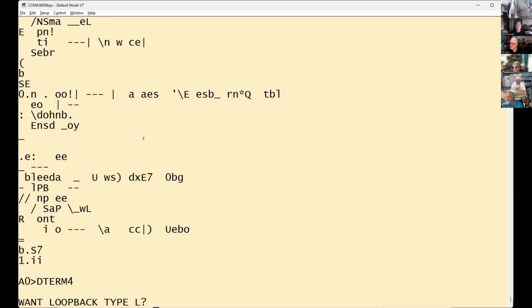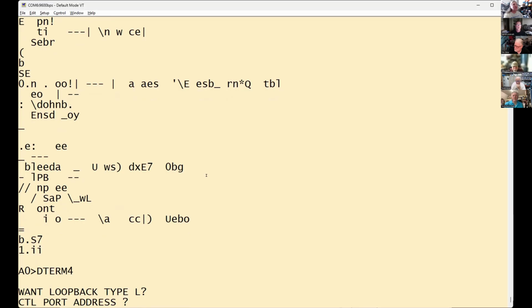No, because what's happening is when you're pressing enter, your modem is saying carriage return line feed okay, and you're just dropping those characters. I know, all that garbage is because the baud rates are mixed. No, Walt, you're at 9600 baud. Your program will not keep up with 9600. I know, that's what I'm saying. That was on port 12. Now I moved the modem to port 20 so I can show you where the real problem is. Walt, change your baud rate to 300 and type AT, and you will probably see an okay. No, I've tried that. I've already done that. I remember, the computer is 6 feet in the air.